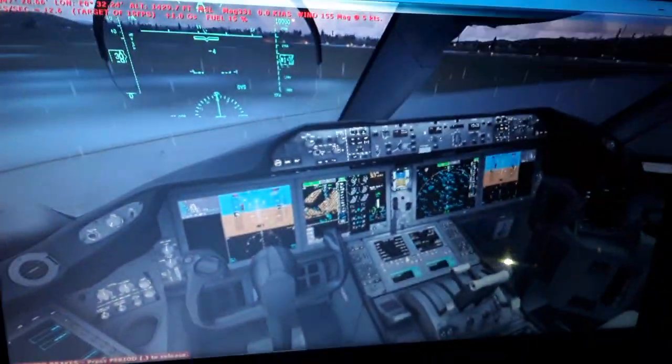Also we have, for takeoff, the center of gravity using the takeoff gross weight, and the mean aerodynamic chord position. I told you the 33% of the mean aerodynamic chord, where the maximum aerodynamic lift occurs. Also where the stall will begin in flight for given angle of attack. You can monitor all the time the stall speed over here.